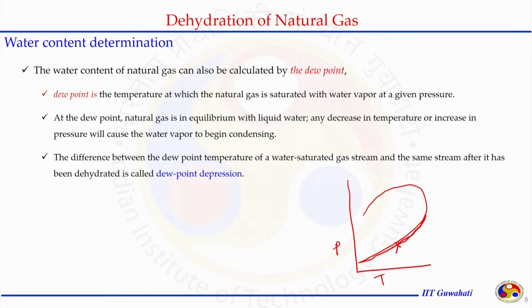When we are increasing the pressure, this will go to liquid phase more than the gas phase, and when we are here, we are having mostly the natural gas in the gaseous phase. Similarly, if we are going at a higher temperature, we will go more towards the gas side, and when we are reducing the temperature, we may enter again in the phase envelope and get the liquid.